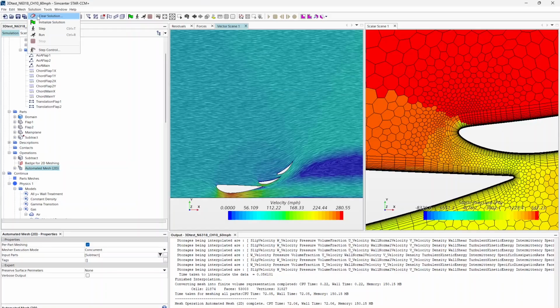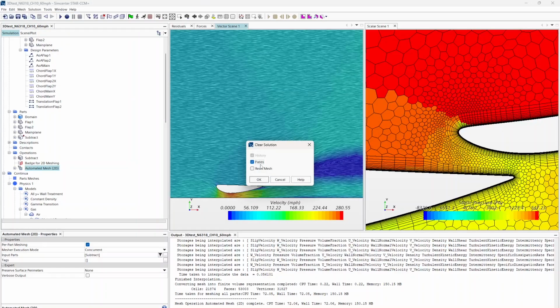And just for the sake of being extra safe, I will reset these fields. But if you're not changing much about your simulation, which we aren't, you can uncheck this, and it will still remember everything that it's solved, all of the velocities at each cell, all the pressures at each cell. It will remember those, keep the simulation going for another 1,000 or less, and so it can take less time to solve because it's already solved for most of the cells. It'll converge much earlier. Actually, let's uncheck it and let's run that so you guys can see how that changes things.